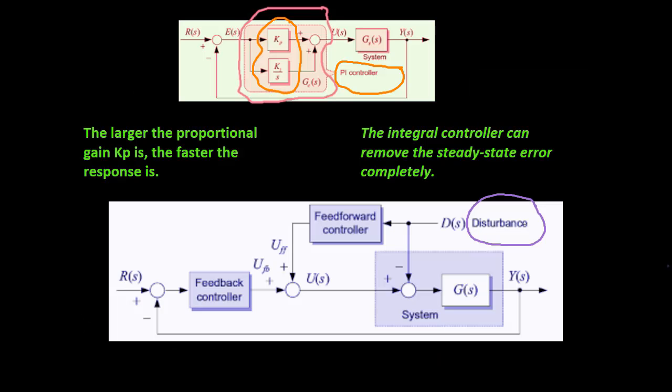Disturbances are always present in the control process. In motor drive systems, for example, the back EMF acts as a disturbance on the current control, and the load torque acts as a disturbance on the speed and position control. Feed-forward control is an effective way to rapidly eliminate the effect of the disturbance on the output. The feed-forward control predicts and compensates for the disturbance by adding it to the control input in advance.